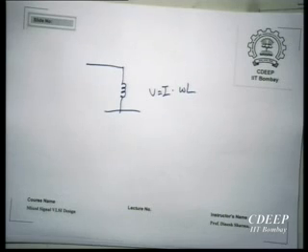Okay, but where am I going to get an inductor in an integrated circuit? That is difficult. Where do I get an inductor? Fortunately, it turns out that if you look at our beautiful beta multiplier, it's actually an inductor. If you put a capacitor at the input, because of the positive feedback and the two GMs, it actually transforms that capacitance into an inductor. Okay. So you've heard of gyrator circuits in analog, it's actually a gyrator circuit.